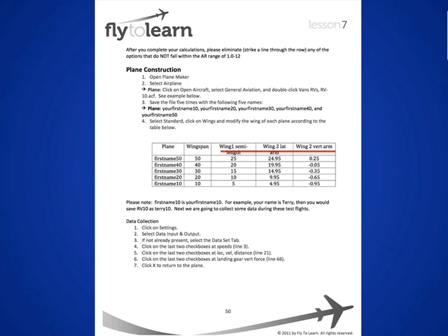Have them copy it and rename it. It can simply be their first name and the number 50 for aspect ratio, or I'd say first name AR50. They would get the Van RV10, go to save it, and save it with their first name and AR50, or their first name and the number 50. And I would do it with 40, 30, 20, 10. Have them just copy it right then. The first class, it'll take them a while to get into why they're copying it, but they'll see in a moment. In future lessons they know to do it and just go fast with it. So you're going to make these 50 copies in Plane Maker. Then they're also going to set in the data where they collect speed.